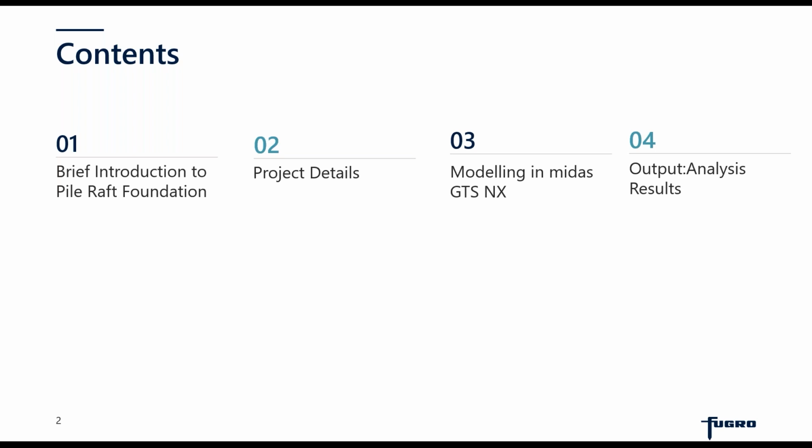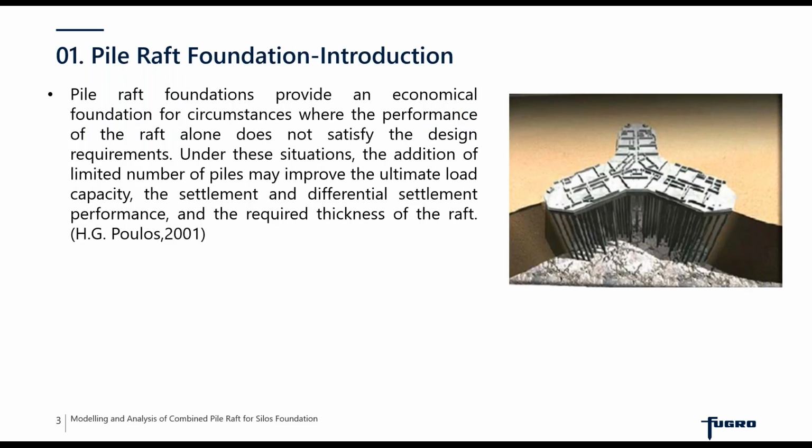So to begin with, first of all, Raft Foundation. Now we all know that Raft Foundation is an economical option in the situation where the performance of the raft alone is not enough to satisfy the design requirements. Under these conditions, we add a limited number of piles to the raft so as to improve the ultimate capacity of the whole system, reduce the absolute settlement as well as the differential settlement, and hence also optimize the thickness of the raft.